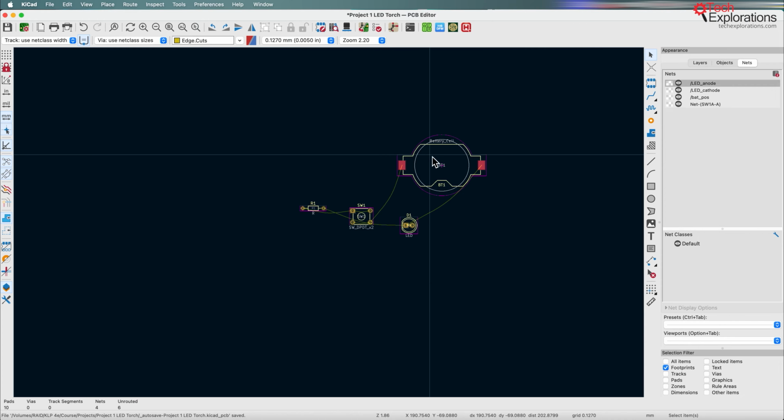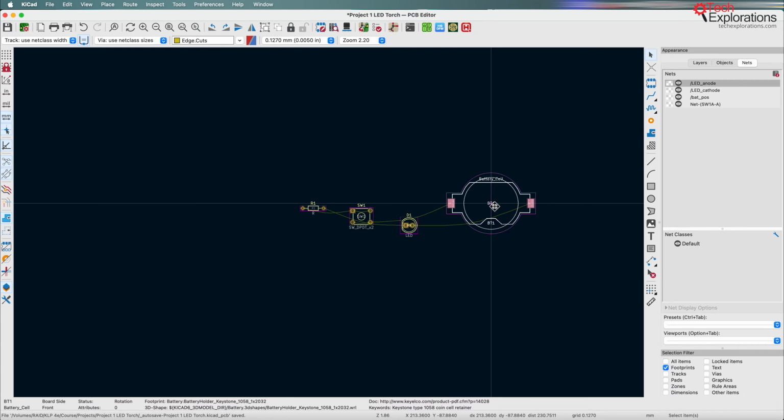Obviously, the biggest component, as I said, is the battery cell, so I'm going to put that towards the back. Imagine that I'm holding the torch in my hand. The battery cell will be towards the inside of the torch, where the outside is where the LED will be. So that also dictates the position of the LED on that PCB. And for the 3D printed enclosure, I decided to attach the LED torch board to the enclosure utilizing a screw, mounting bosses, or sliding rails, or perhaps a combination of those. So the board itself should include one screw mounting hole. With all these constraints in place, I decided to continue.